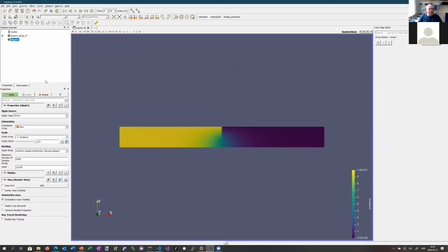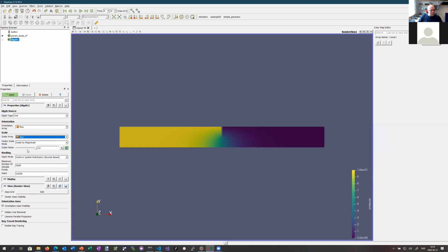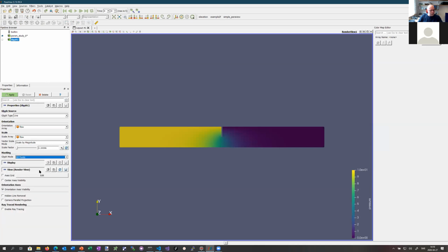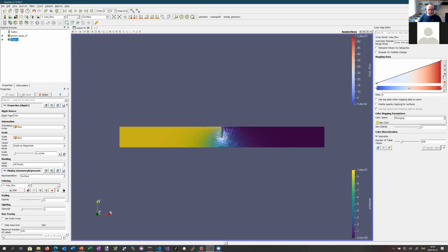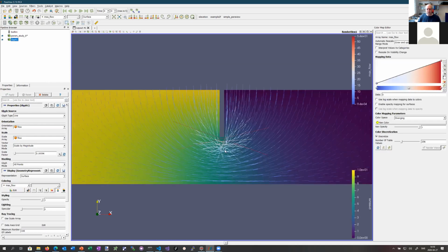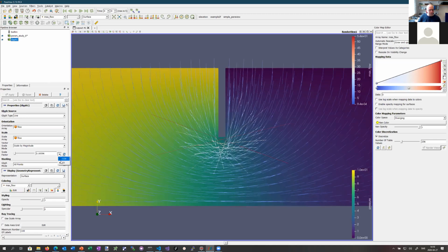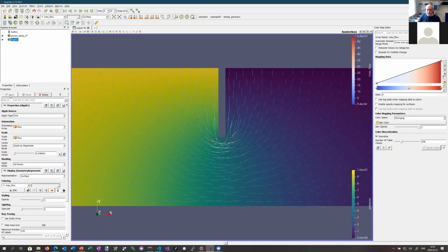So we do, we want to orient the vector by this one, and we put line, scale array by flow, auto calculate, all points, apply. So they're a bit big, so we scale them. Like that. Now you also see you can create a color scale for the magnitude of the flow here as well. So it creates a different color scale here.